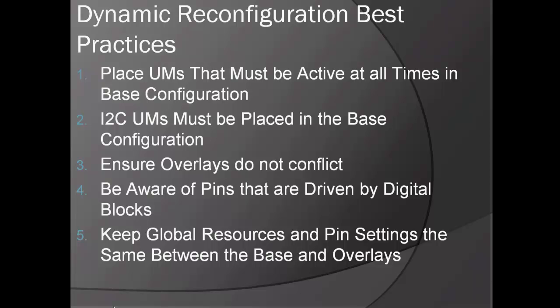Number 3, ensure that your overlays do not conflict with each other or override each other. PSoC Designer has no way of checking to see if a block is free before loading an overlay, so you, the designer, need to ensure that the block is free before loading something into it via an overlay.